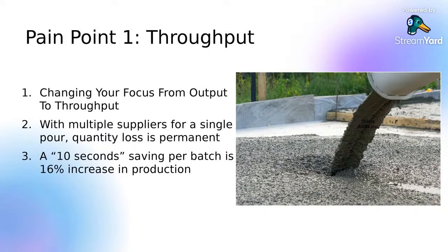You have to fill it. Let's say it is 1 cubic meter per minute capacity. You need 6 minutes or you need 8 minutes to fill up that transit mixer. But if there is a delay of 10 seconds when the one transit mixer leaves and the second one comes in position, what does happen? With this small delay, what happens is you start losing productivity, and this loss can be as high as 16%. That's what we have calculated at a number of batching plants.